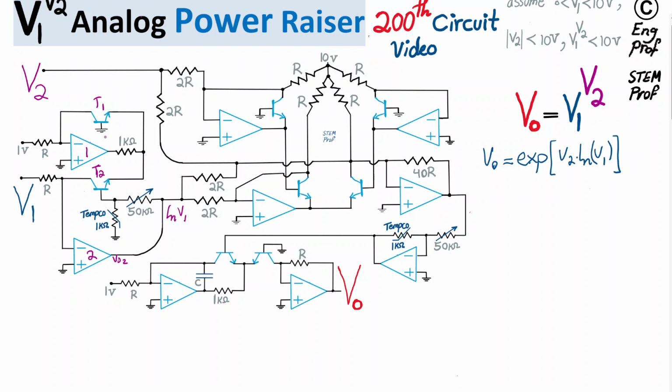So what I can say is you can see that the base of the first one is 0, so we have 0 volt here. And then from the base, we have one base emitter drop, which is VBE1. And then from the base of transistor T2, VB2, we have another base emitter drop, VBE2. So effectively, I can say that VB2, I'm going to write it here, is equal to the voltage of base emitter of transistor 2, minus the voltage of base emitter of transistor 1.